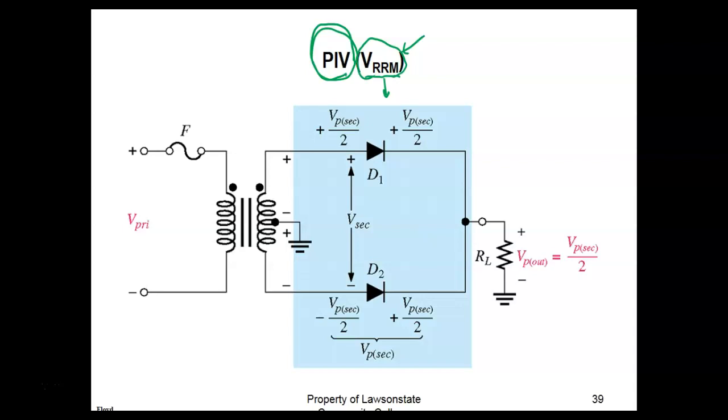So this is why silicon has been around for a long time, and silicon is readily available. You know, sand is basically silicon. So silicon is readily available, and plus it's got better temperature characteristics than germanium. Germanium was the first one they used, and there are still some germanium diodes out there that take advantage of that very low VF, of around 3/10 of a volt or 300 millivolts. So they're still out there, but silicon is by far the most widely used semiconductor making these solid state devices.